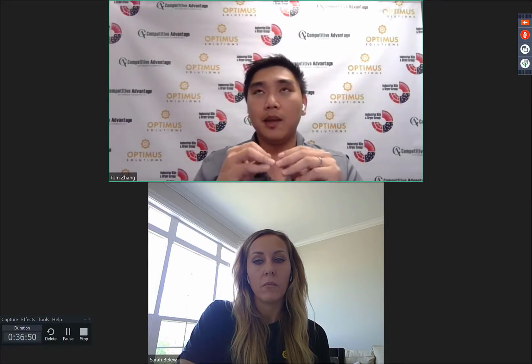But the key there is your CO. If your CO is 1,000 or more, typically that's pretty bad. We try to make adjustments when we see something above 1,000, or we recommend you guys make an adjustment. If not, then if your CO is maybe 20 and your NOx is maybe 20 parts per million, under 50 is kind of our general rule of thumb, then that would be a good combustion.